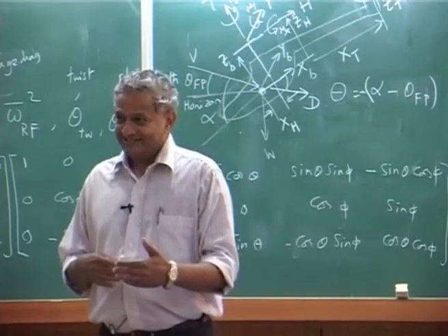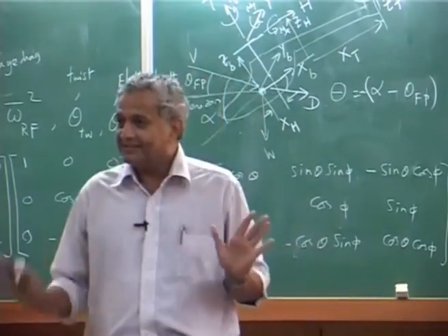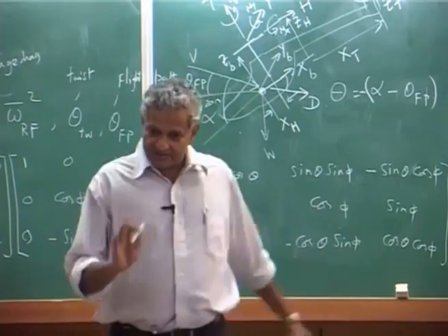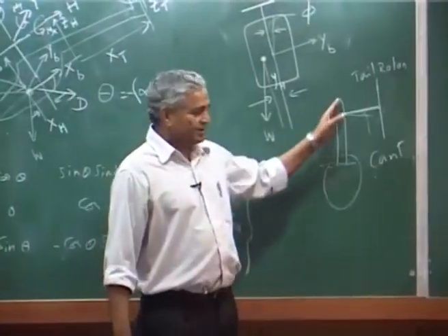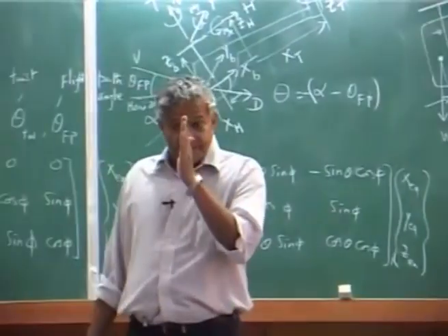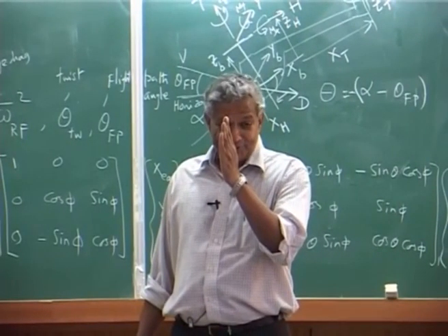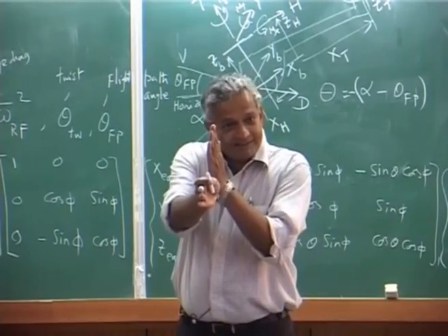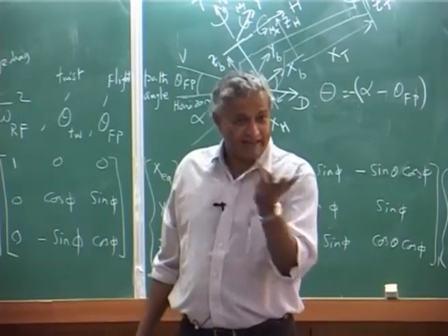Engine may have power, but the pilot cannot fly, it will not be in equilibrium. So, that is why they introduce all the fixed surfaces. Now, you may ask why they have a vertical fin. The vertical fin will not be at 0 degrees, it is slightly given 1 or 2 degrees to the longitudinal line of the helicopter, at an angle of attack.